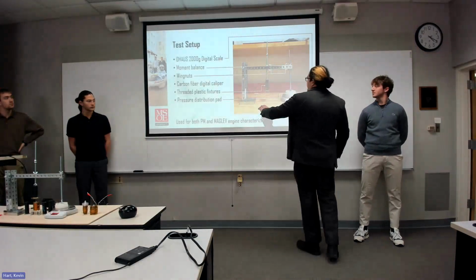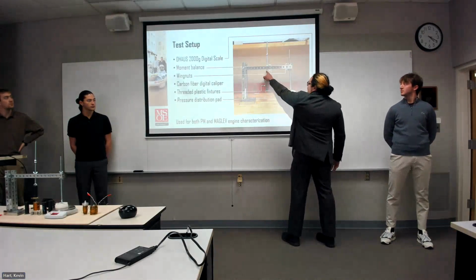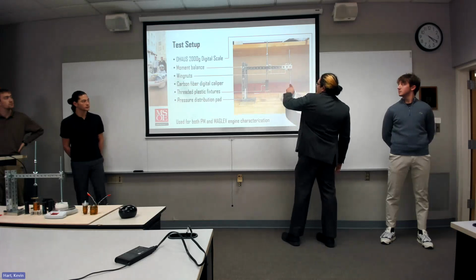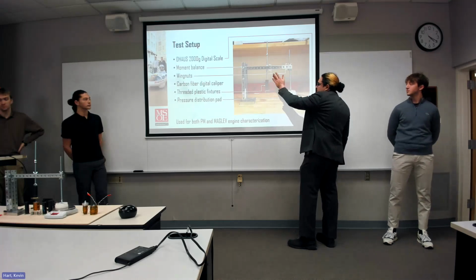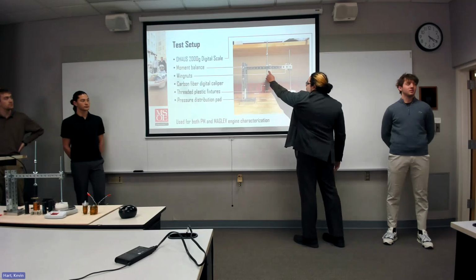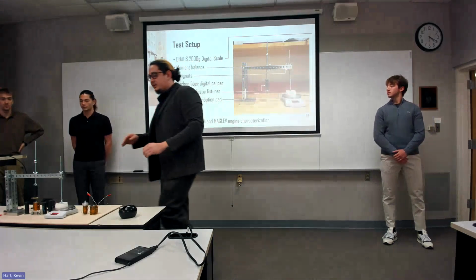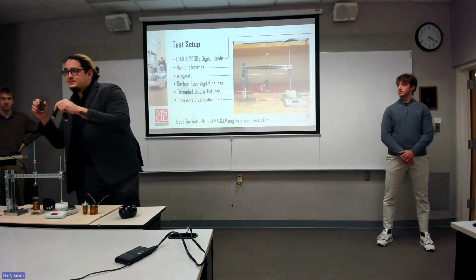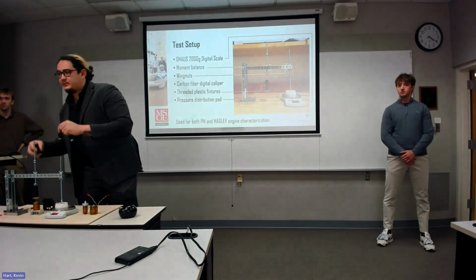So it's basically a lever system with a frictionless point right here. Ferromagnet sample suspended right there, and the weight distribution going to the scale. Moment balance provides you with a simple equation to get the actual magnetic force. And the benefit of this setup is that we can adjust the wing nuts to get a very, very certain distance between the magnets, between the samples. Additionally, we made interchangeable tips to see the effects of the coils and magnets on different sides of ferromagnetic materials.